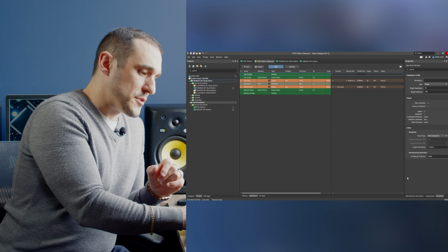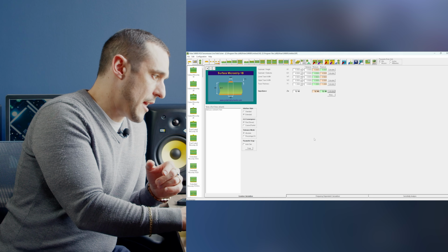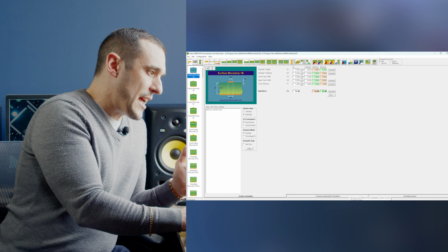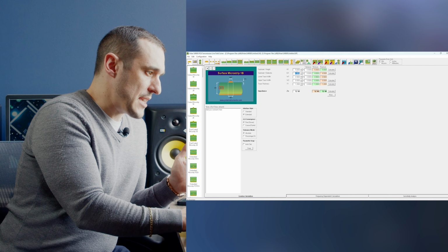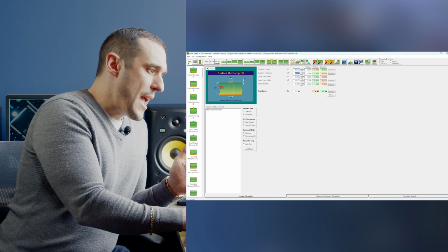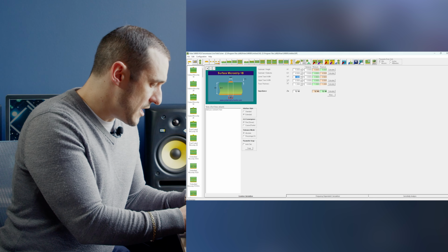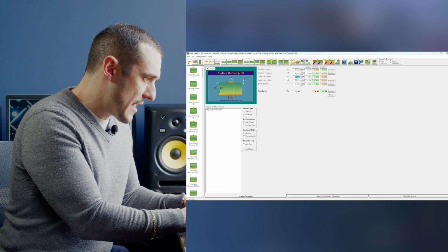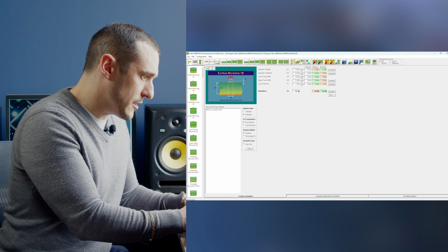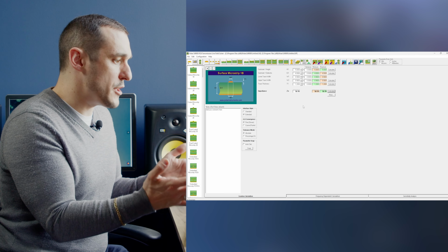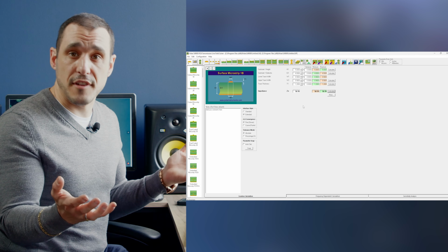and the S parameters. So here I have Polar SI9000 open. Here I have a surface microstrip that I'm going to use, and I've replicated the substrate thickness and the dielectric constant here. And you can see here if I put in that same value for the trace width, and then I replicate that up to the upper trace width and calculate the impedance, you can see here that Polar tells us that the impedance value is 50.95, or basically 51 ohms.